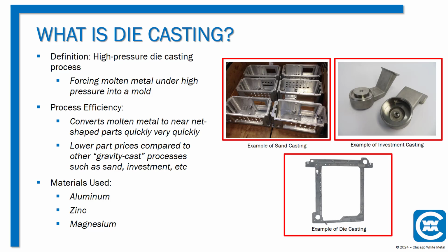The image below here is a high pressure die casting. So, fairly thin wall, very intricate features that can be cast, and minimizing any secondary operations, whether it's machining or other things that need to be done. That's the goal of a high pressure die cast part.